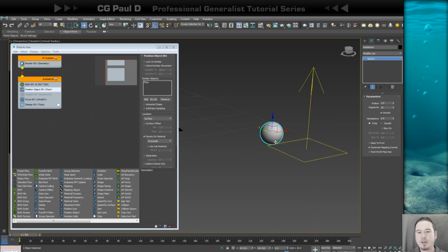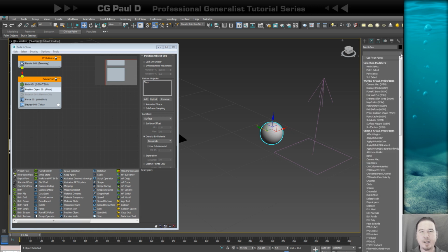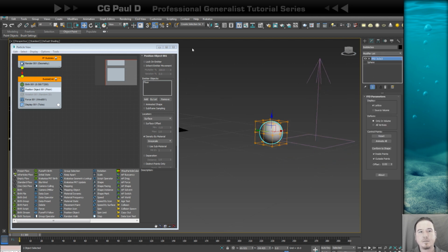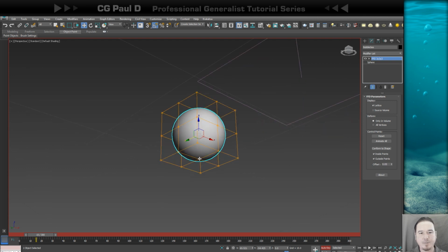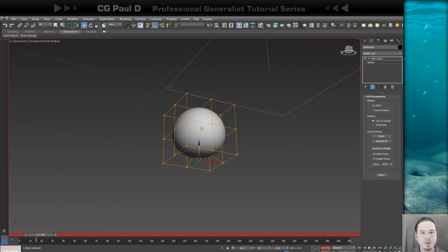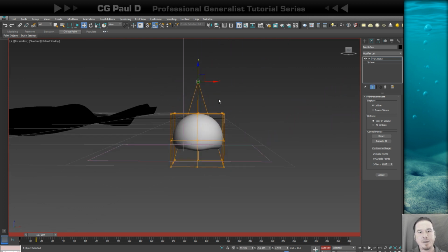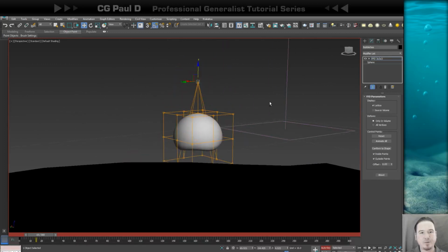And again, I just want to animate it a little bit using a couple modifiers. And in this case, we're going to distort it, kind of creating a billow effect and cycle that through to help out. So we're going to do an FFD 3x3. And we'll go ahead and turn on auto key, and we're just going to animate a cycle within 30 frames. So I'm just going to move to frame 15 and grab the underbelly control point. And I'm just going to pull it right on through the top a little bit to create this billowing effect.